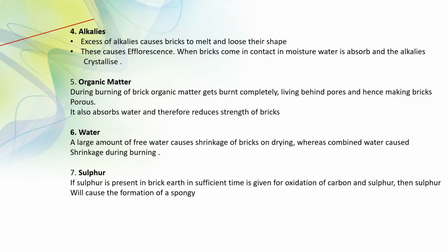And next, alkalis. Excess of alkalis causes brick to melt and lose their shape. This causes efflorescence when brick comes in contact with moisture, water is absorbed and the alkalis crystallize. Then organic matter. During burning of brick, organic matter gets burned completely, leaving behind pores and hence making bricks porous. It also absorbs water and therefore reduces strength of brick.